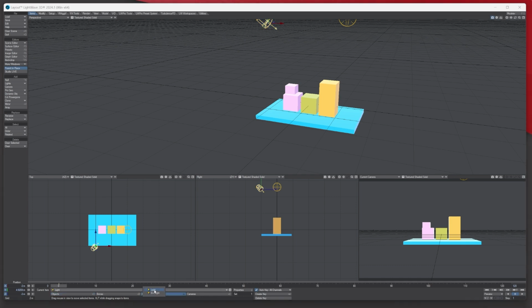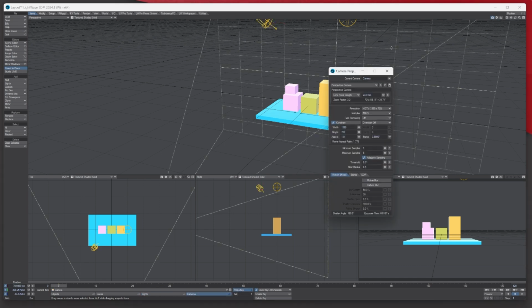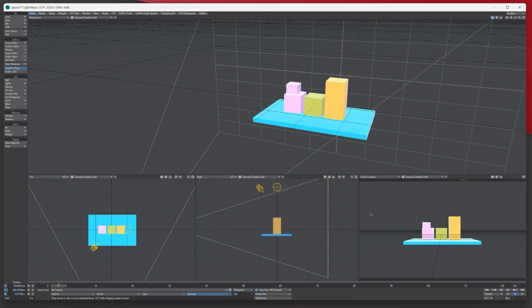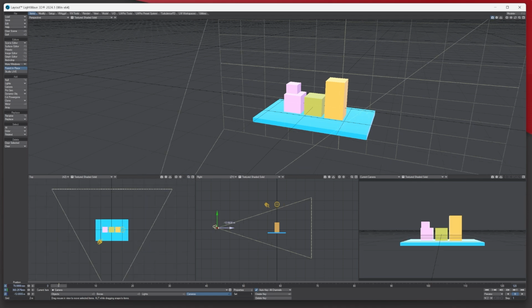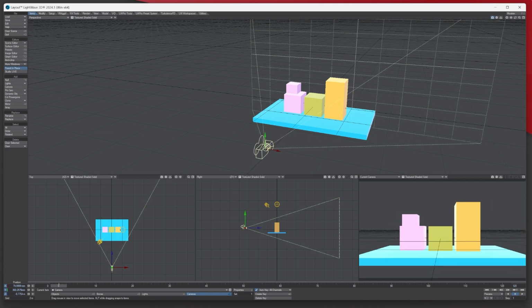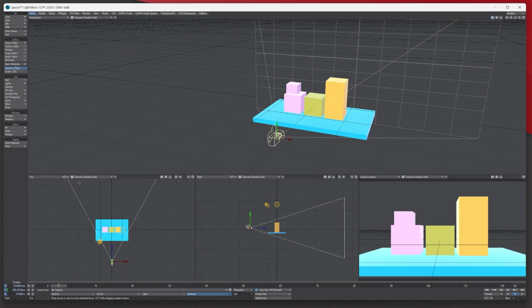So when we click on lights, you've got different lights, cameras we'll use, and whenever you click on one and you click properties, it brings up the information about them so you can start to edit them. So currently the first thing I'll do is let's move our camera into place. So I'm on my camera, which brings up the handles, and then you just literally grab the handle and bring it the way you want it. So with moving, I always use the right and the top, and usually I have them at the drop down the way you want to view the elements as wireframe, like so.